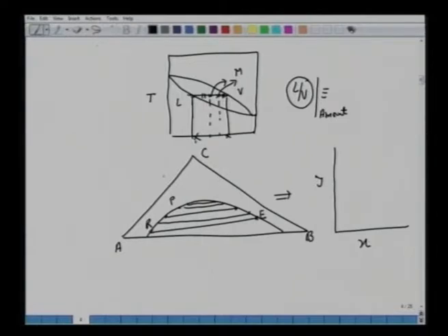All right, so now we are going from this triangular diagram to this Cartesian coordinate system with Y and X. Just take this Y here, we call it extract, with the weight fraction Y, and all the raffinate as X. This is the plait point, and plot Y versus X with this as a 45-degree line. You will expect a curve like this. This will be the most general. So beyond P now, Y is larger than X.